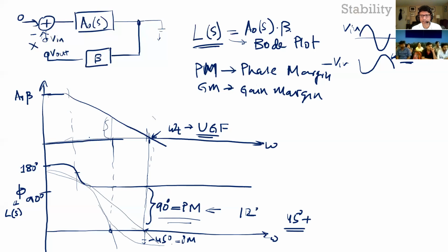Now gain margin, you want it to be less than 1. So let's say in dB, this was 3 dB. That means this is unstable now. So you don't have any margin. If this was minus 3 dB, then you're stable. In other words, when the phase goes to 180 degrees, you want to make sure there is no gain left in your loop, otherwise it'll start oscillating. Or in other words, when the gain goes to zero, you want to make sure the phase has not gone to 180 degrees. So you can look either way.